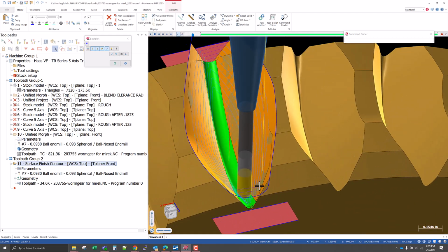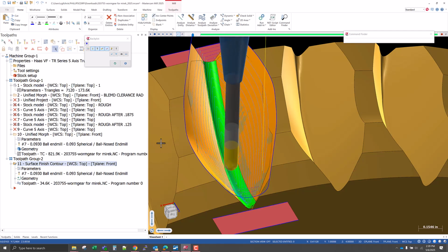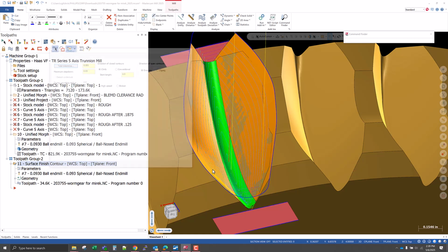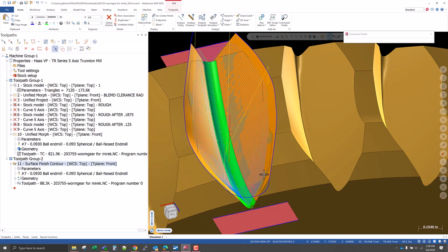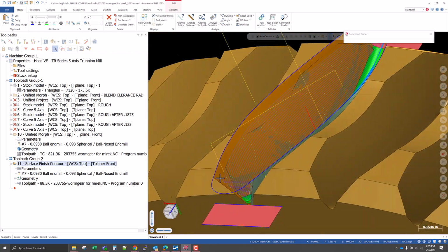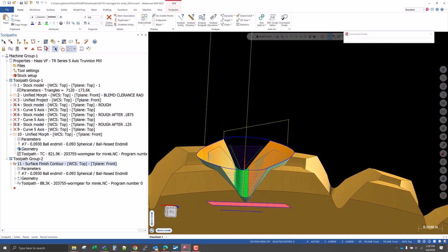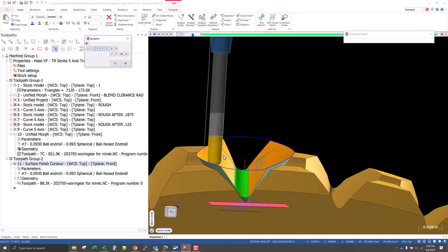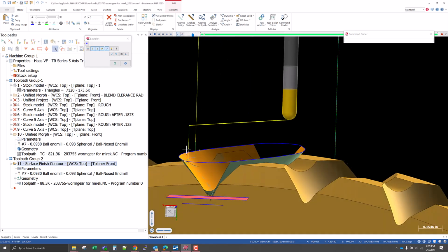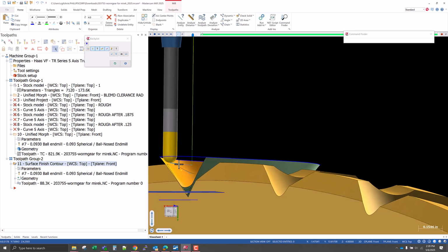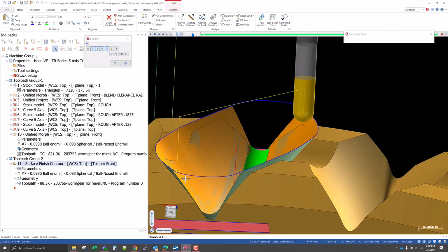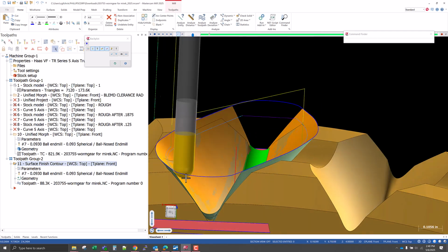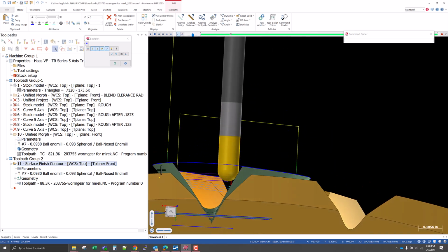And now we can adjust the step down, right? We did a nice, easy 30 thou step down for the calculation. We can now go in here and make this 10 thou. Say OK. But what we're probably going to end up with, yep, we have all these extra passes now, especially kind of up at the top. So you can see that it barely makes a pass here. Barely makes a pass, and we're up above the geometry completely. So it barely makes a pass, does this weird kind of little step. Now it gets down to where it's actually cutting.